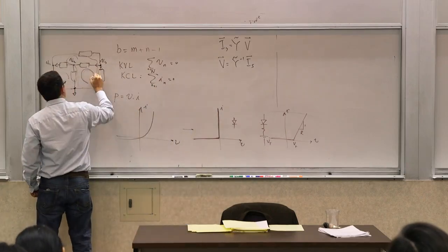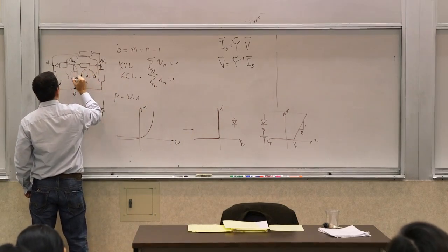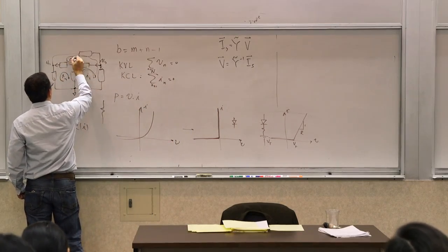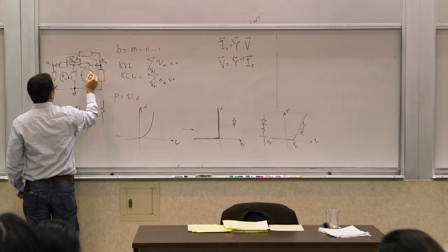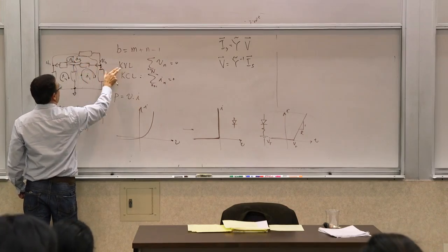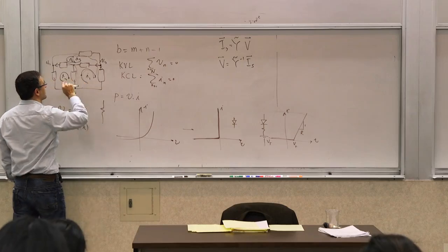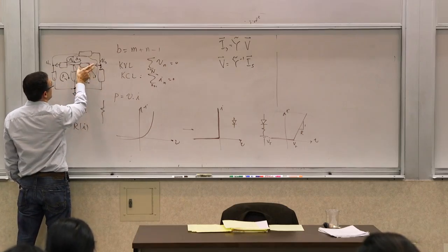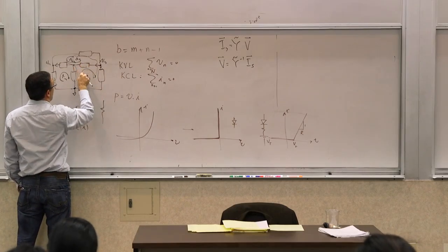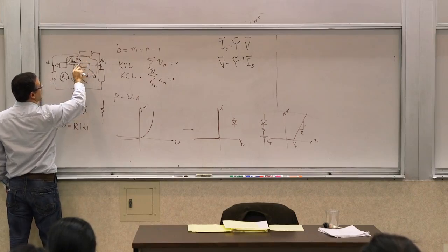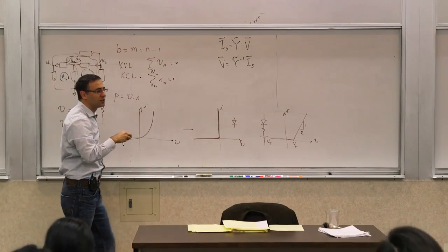We also had a parallel, a dual analysis, which was the mesh analysis. We saw that you could actually define mesh currents, I1, I2, I3, and basically what we could do, we could write, for example, the KVL now using the mesh currents. For example, the voltage across this thing would be this element times this current minus that current, because that's a superposition of these two mesh currents.